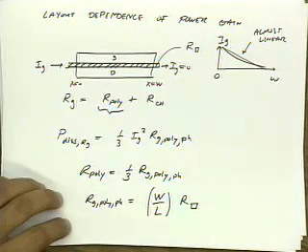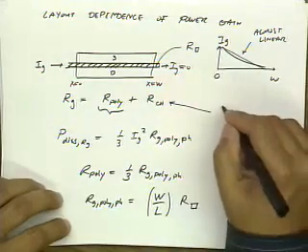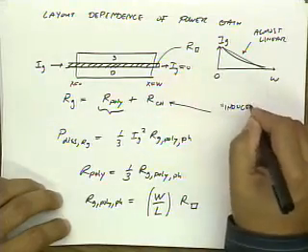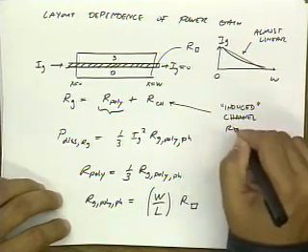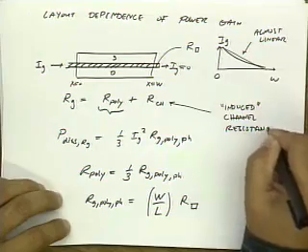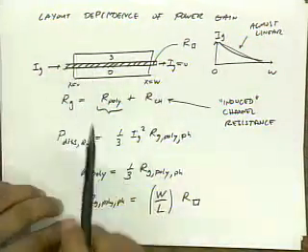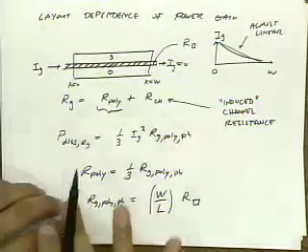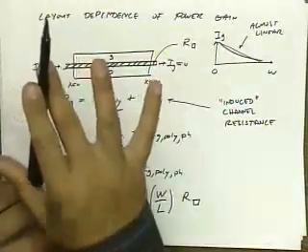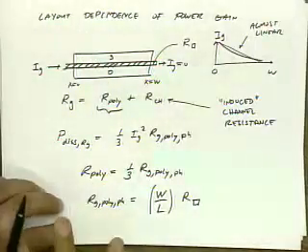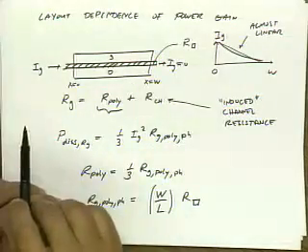Okay? Clear? Now this term is a little bit more tricky. This is the induced channel resistance, and it's proportional to the resistance of the actual device. It turns out that because the gate current flows into the channel and then it flows into the source and drain, because the channel is resistive, that actually contributes a resistive part into the input admittance.